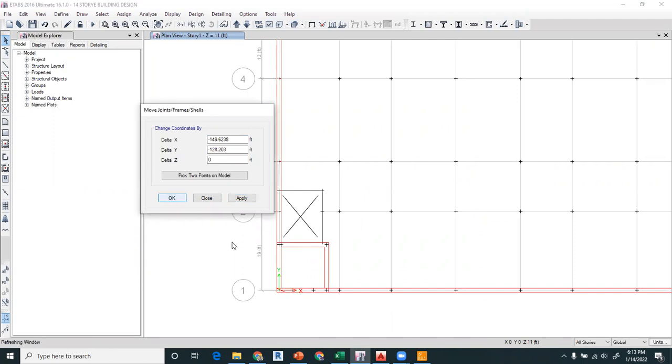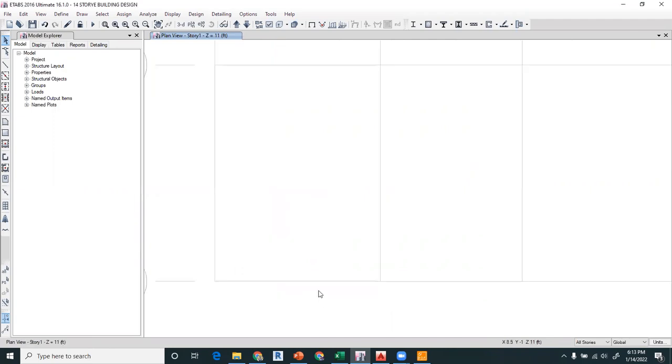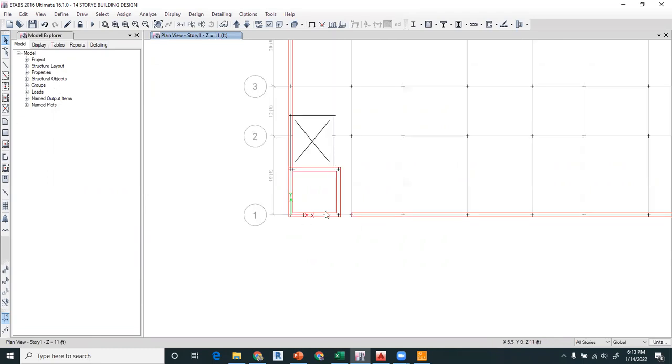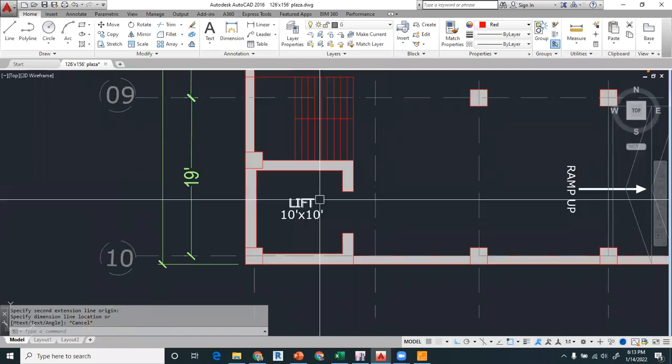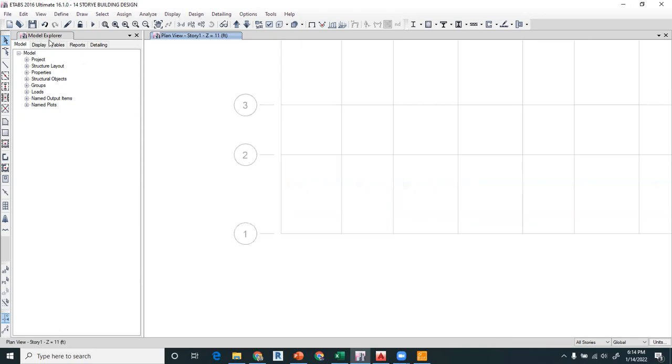So this left wall has been placed in here. We can delete that retaining wall, but the face of this left wall is this way, but in our model, you can see it is in that location, right? So you can give its local axis, and you can rotate that as well. But let us use this command again.